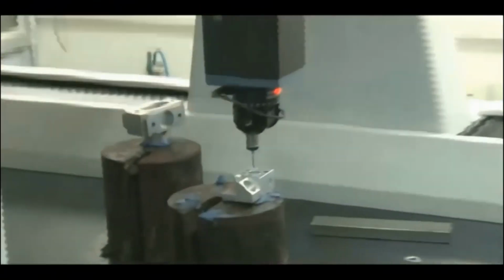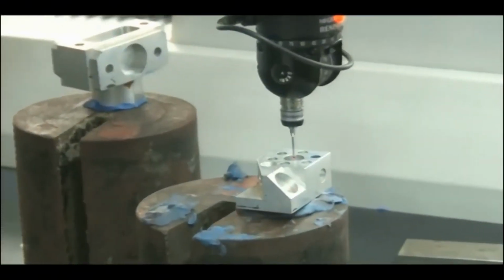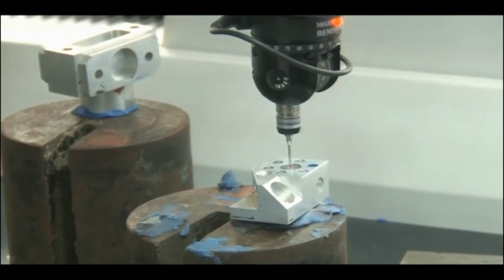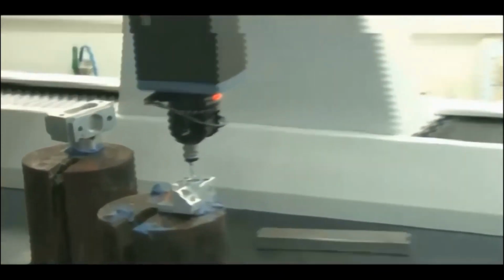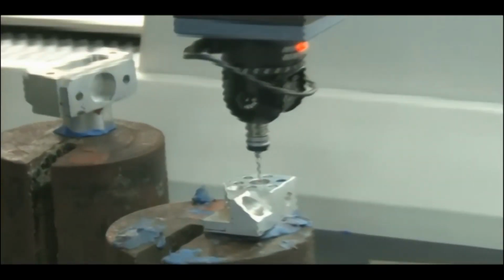So, 3 points for plane was selected. For cylinder we need 8 points, 4 points in one plane, 4 other points in the second plane. 4 points in one plane will give me the location of the cylinder, that will mark one circle. Another 4 points at a little depth than the initial plane would give the second circle. These 2 circles would help us to generate a cylinder.